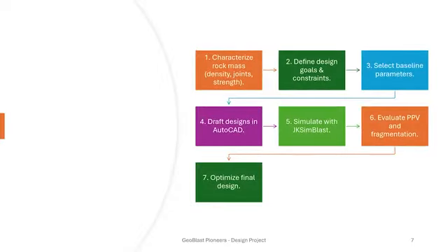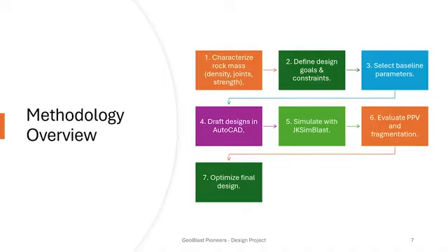Our methodology followed several key steps. First, we characterized the rock mass and site conditions at the spillway area. Then we defined design objectives and constraints, followed by collecting baseline parameters from similar Sri Lankan quarries. Next, we developed preliminary designs using AutoCAD and simulated them using JK-SimBlast. Finally, we analyzed fragmentation curves, vibration data, and costs to identify the best model.